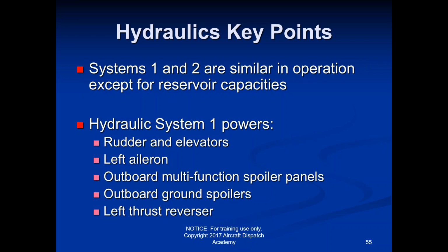When you go back and talk about the pumps, like I said, there are 3 systems here. Each of them has 2 pumps, so there are 6 hydraulic pumps total. But the ultimate thing is that we have 3 hydraulic systems, and in order to fly, you need 2 of them operating at all times. A lot of these aircraft systems that we go over, we have 3 of, and that's really just to allow us to still be able to fly if one of them goes out. We have a backup.